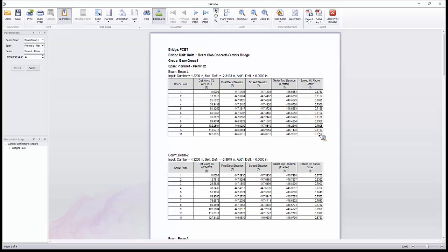Yeah. And also in the steel, we give you the camber diagram itself, right? When you design with Leap Steel. Right, exactly. You can get a similar type of report out of LeapBridge Concrete as this, but as Alex said, on the LeapBridge Steel side, we even give you some more. We'll actually draw the diagram itself and give you a breakdown at the 10th points of each of the loads, and you as the designer get to select what loads to consider for the camber itself. So it gives you even more control there.